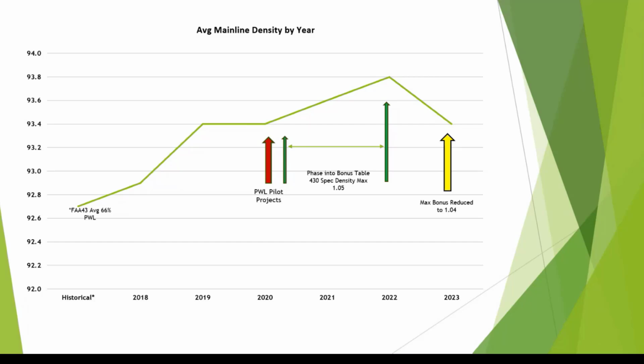That was the average. If you ran a percent within limits, you know, how much of that was actually within the spec limits, in this case, basically greater than 92.0, those numbers showed roughly 66%, only 2/3 of them. So 1/3 of the roadway was less than 92% density, which means more air voids, which means more moisture penetration, which means more potholes and so on and so forth.